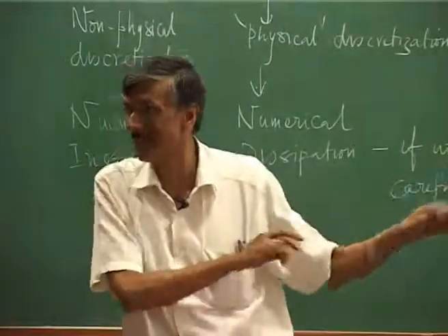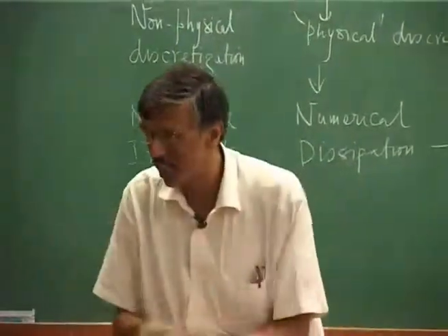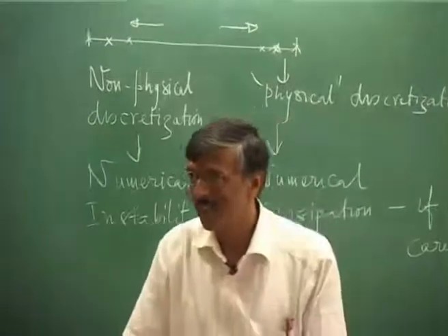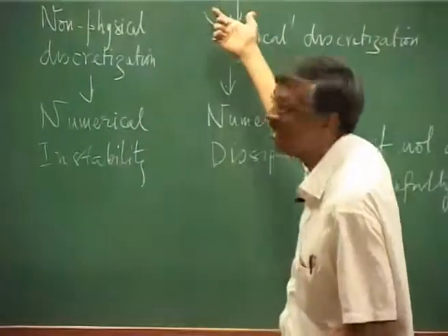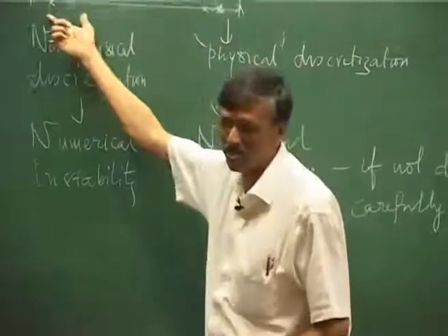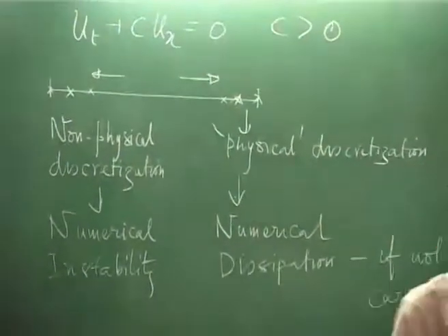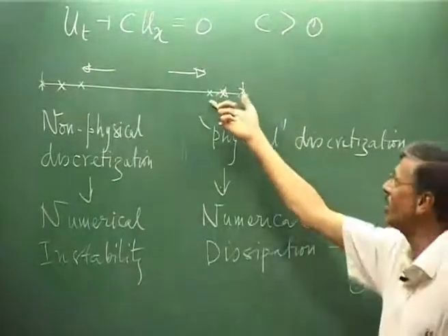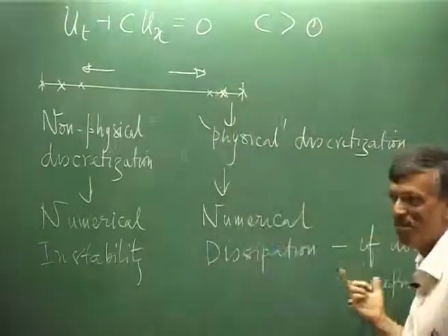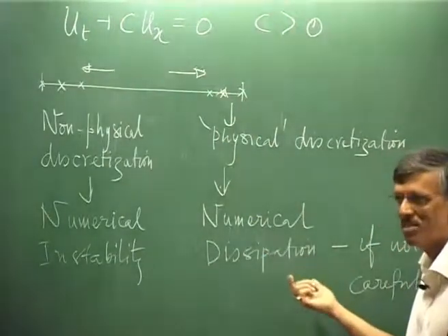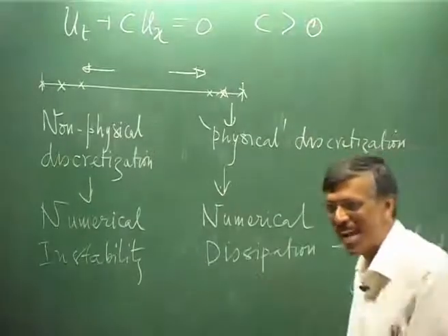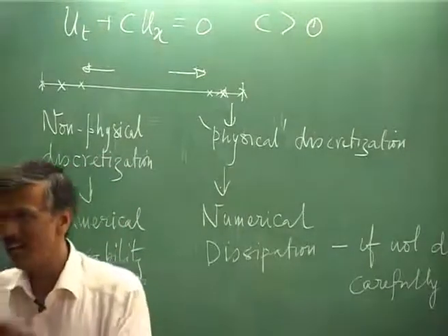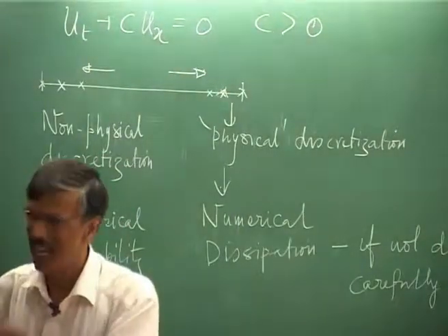I mean, you are doing a perfectly central scheme. That is why we are looking at the central scheme. We do not want to impose additional dissipation. So from j equal to 4 onwards, you are in safe territory. In a problem like this, I am always, in a spurious sense, exciting the system from the left hand side. And in the same way, when I am coming to the last 3 nodes, if I am not careful, I am adding numerical dissipation, so those errors decay also. So, without your knowledge or intent, you are exciting the system spuriously on the left and damping on the right.